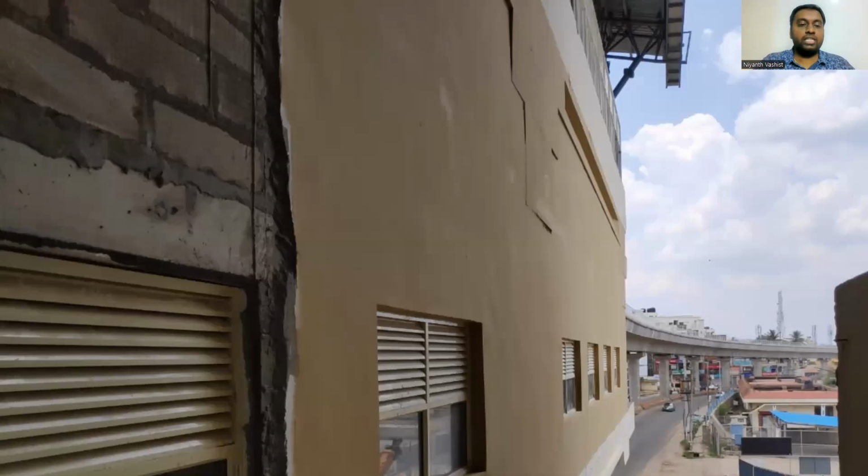Now, if you look at the finish of the product also, you can see the section as well. There is blockwork, plaster, thick plaster, around 20 plaster, and of course the painting layers: first coat, second coat, primer, putty, all those things. Very rarely do we use chajjas in metro. One, because of aesthetics, second, because of the louvers. Now if you look at all the aluminum horizontal bars that are there in the windows, those are called louvers. So louvers will be used in these kinds of projects as well.